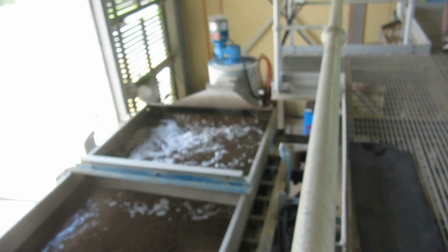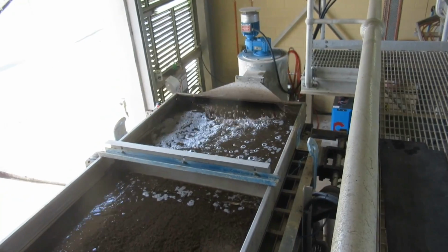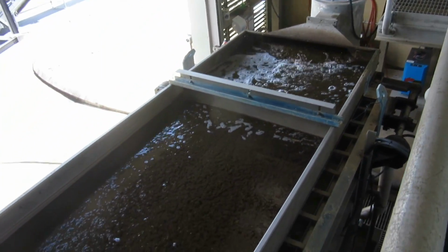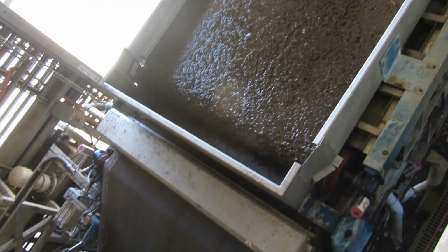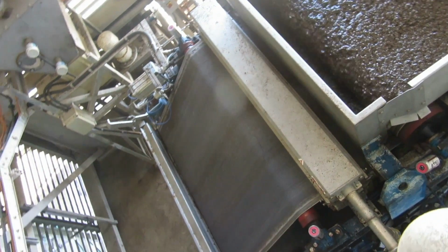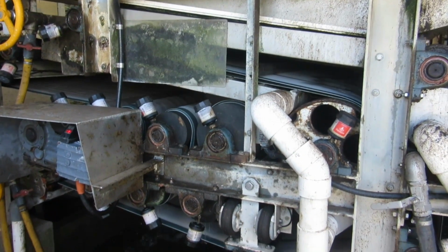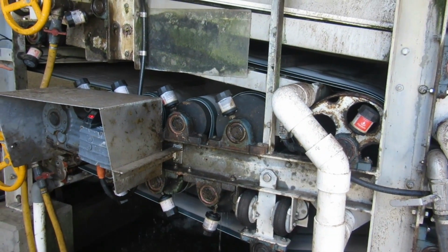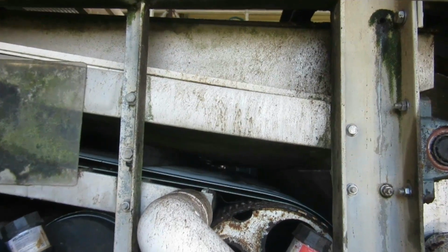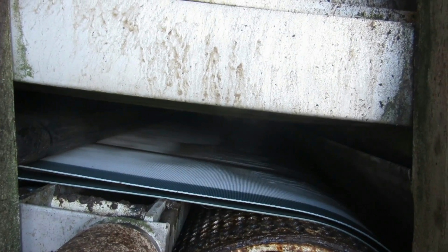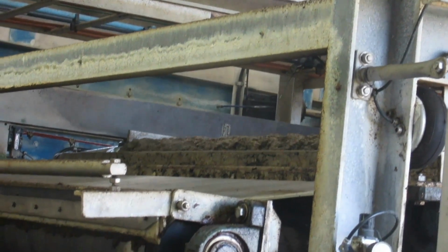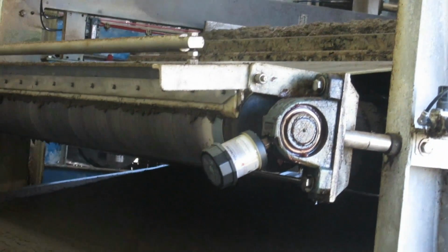This WAS is pumped into the belt press receiver tray and mixed with a dose of polymer to further thicken the mix. The sludge mix is then steadily fed between two semi-porous filter belts, within which the sludge material is squeezed through a number of rollers. This compression force works with gravity to remove a substantial amount of liquid and results in a 15% solid material